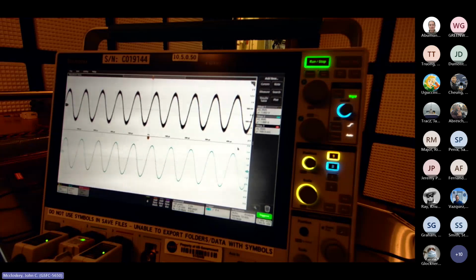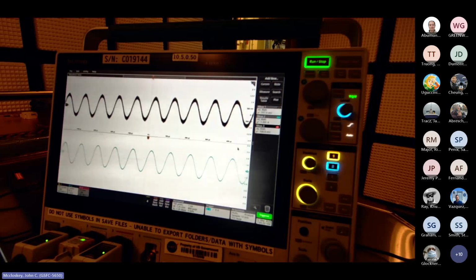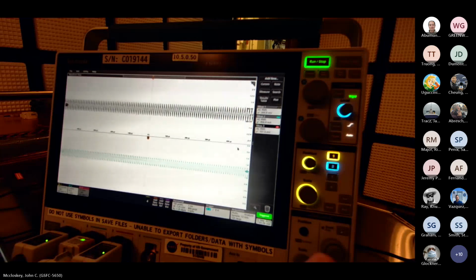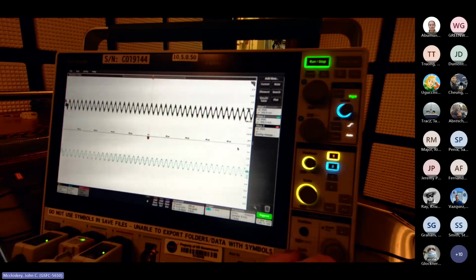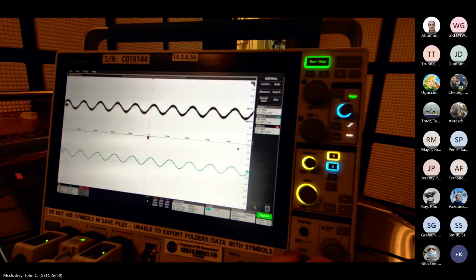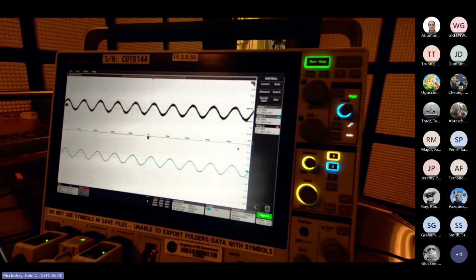And I'll drop the amplitude about 6 dB again, and now we'll go up to 100 kilohertz. All right. Now the level is dropped, and the transformer is starting to get a little bit less efficient. We're starting to push it pretty hard again, getting up to 150 kilohertz, so we need a little more signal level to get our 1 volt.